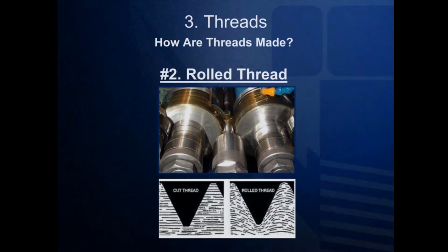Here we will describe some of the definite advantages of roll threading. First of all, it's faster. So your standard grade 5 and grade 8 hex cap screws were definitely produced on huge production runs that use roll threading to create the threads.